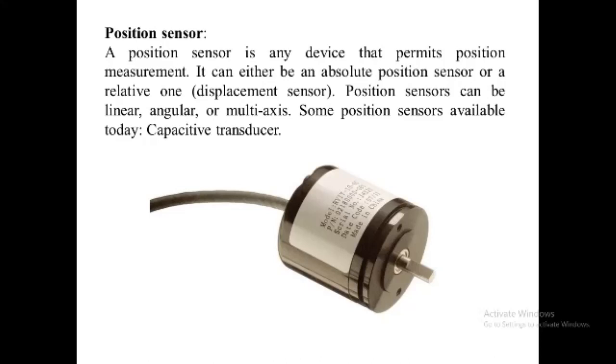Some examples of the simple potential sensing circuit. While the resistive potentiometer position sensor has many advantages, as it has low cost, low technology, and is easy to use, as a positional sensor it also has many disadvantages where, due to moving parts, it has low accuracy, low repeatability, and limited frequency response.